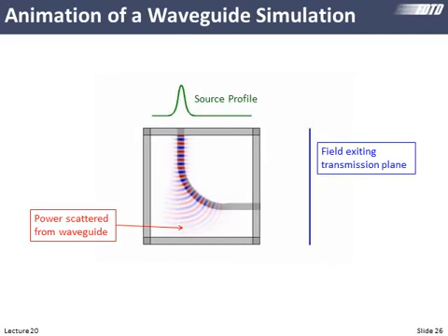So we see the green profile source up top, and notice that that source did not immediately turn on. It sort of eased into the source. We could see it kind of going around the edge, but a lot of it is leaking out. And of course, whatever leaks out hits the PMLs and gets absorbed, so it doesn't reflect back in.